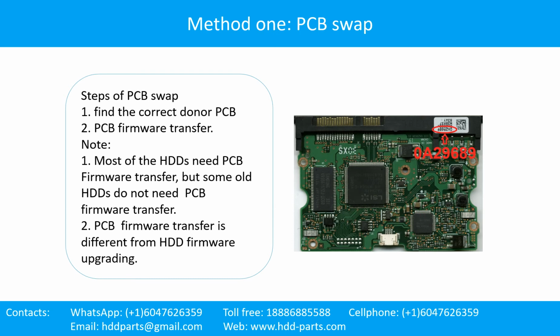Step 1. Find the correct donor PCB. Step 2. PCB firmware transfer. Note: 1. Most of the hard drives need PCB firmware transfer, but some old hard drives do not need PCB firmware transfer. 2. PCB firmware transfer is different from hard drive firmware upgrading.